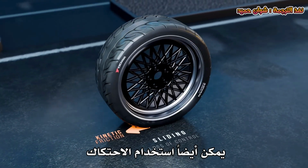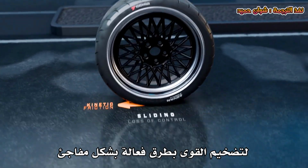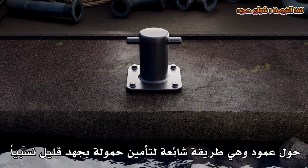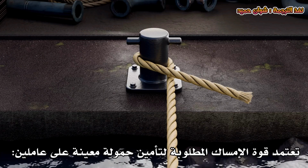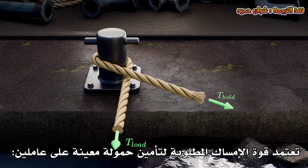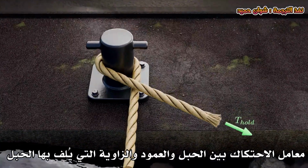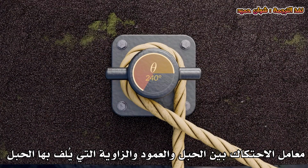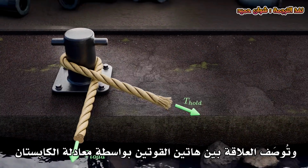Friction can also be used to amplify forces in surprisingly effective ways. Take the example of a rope wrapped around a post, a common method for securing a load with relatively little effort. The holding force required to secure a given load depends on two factors: the coefficient of friction between the rope and the post, and the angle through which the rope is wound. The relationship between these two forces is described by the Capstan equation.